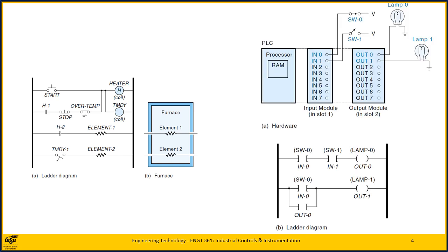On the other hand, the PLC ladder diagram is basically a logic diagram consisting of symbols, called input and output instructions, and a rung becomes continuous when there is a logical true path from rail to rail. If there is a continuous path of true input instructions from the left side of the rung, then the output instruction on the right side will become true. Therefore, writing a PLC program involves placing instructions in the rungs so as to obtain the desired result.